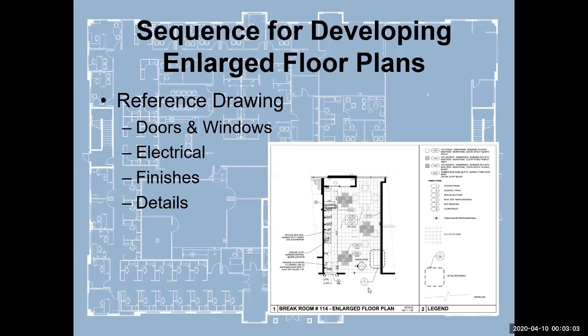So what you'll observe here now is that we've taken and put the floor grid in. These are 12 by 12 tiles for the simple reason that the client wanted a very specific pattern in that room. And so we identify what the field color is for the floor, and we pick out the two accents, and they're colored in with different field colors so that the contractor can see the pattern that we want to have and the approximate placement.